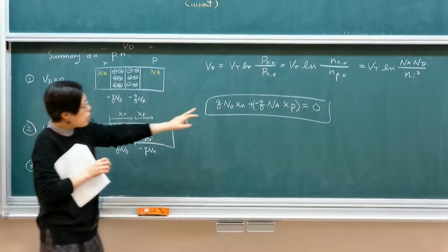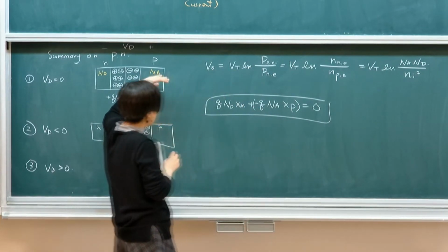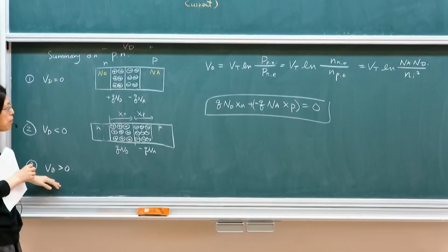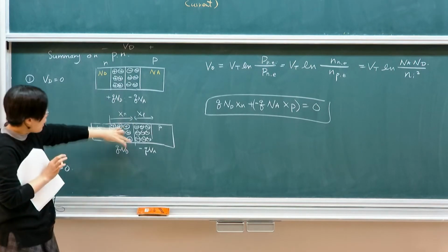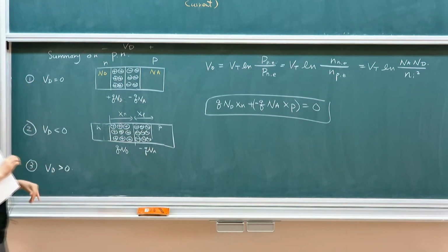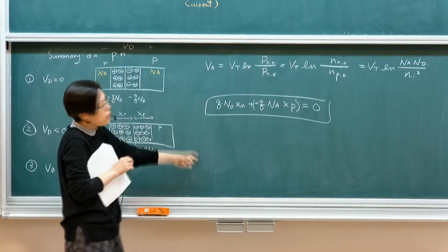So the ratio between the depletion regions, in forward, reverse, any type, has to hold. Ratio meaning the depletion width ratio. If my doping level is the same, then my widths are always the same: Xn equals Xp if their doping concentration is the same. If they differ by 10 times, the ratio will be inverse by 10 times. So it always holds in all three conditions.